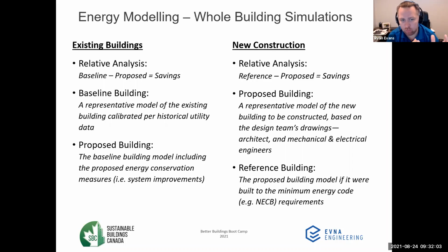When you make an envelope improvement, and you make it better, you're essentially putting less of a load on your heating and your cooling system, and that usually impacts it in such a way where now you can size your equipment. You can put in smaller pieces of equipment to achieve the same performance levels.